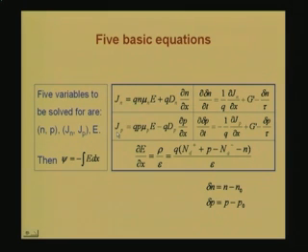Then we saw the steady state approximation or assumption, according to which this particular time varying term here in the continuity equation for electrons and a similar term for the holes can be set equal to 0. In a deviation of this approximation called the quasi steady state approximation, we can still set these two terms as 0, but the equality sign is replaced by an approximately equal sign here. That means the right hand side of these two continuity equations are approximately equal to 0 in quasi-static approximation.